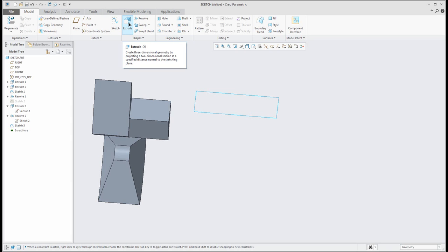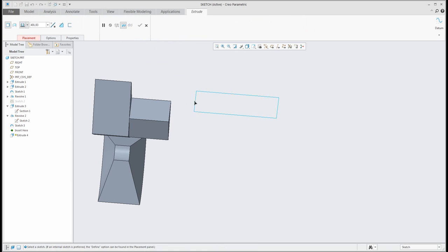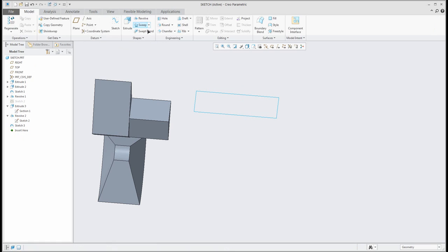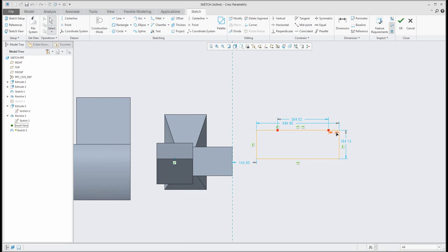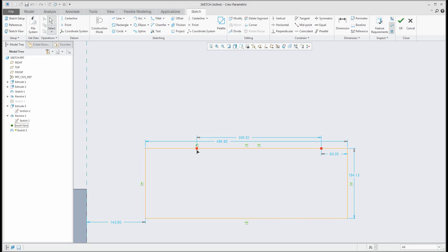And then how do you know it? Because you would like to use it for the extrude feature like here, and it's not working. So I'm sorry, it's not working, we have some problem. And then you have to go back into sketch 3, edit definition, and have a look and investigate what is wrong. Over here we have some inspect features, for example, closed loop or highlight open ends. You can see open ends.